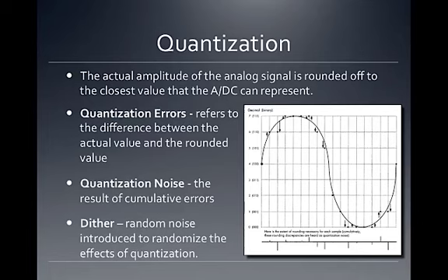Kind of a quick aside, if you were to translate the amount of noise involved in vinyl records, that would only be 13-bit audio. So moving to 16-bit is pretty good to begin with. Going to 24-bit, that noise floor, that quantization noise, is really, really, really soft. You'd have to amplify the signal quite a bit in order to hear that noise anyway.